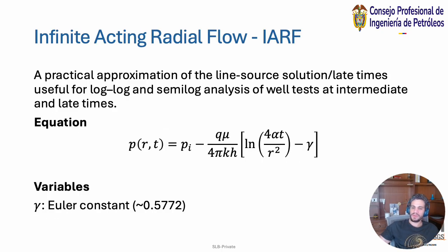So now we're moving on to the infinite acting radial flow, most commonly referred to as IARF. And that is a practical approximation of the line source solution at late times, and it's useful for log-log and semi-log analysis of well tests at intermediate and late times, right? So here we're really looking at well test analysis, and this equation is very relevant for that.